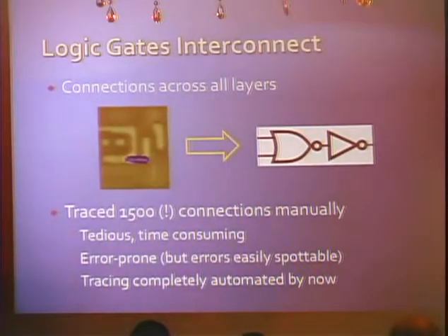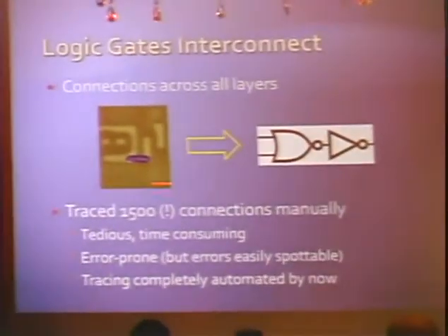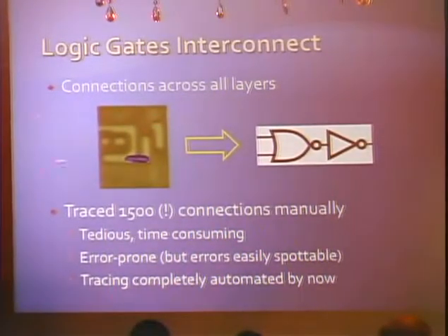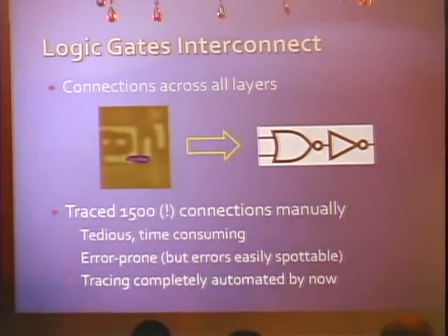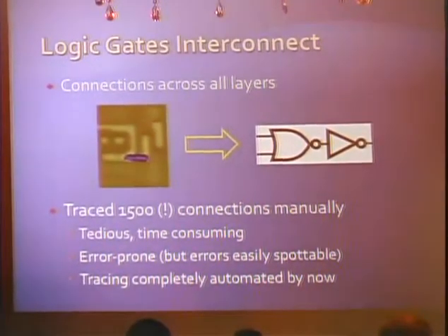So back to reverse engineering. What we have is now a map of all the different logic functions on that logic layer. But there's still 3 layers on top of that where these different functions are interconnected. And so those are crucial to the functionality as much as the logic cells are. So what we want now is to combine the information of what gates are where with what is connected to what, and then reconstruct the circuit diagram, something like this representation.